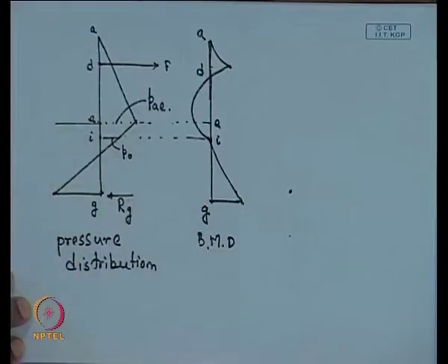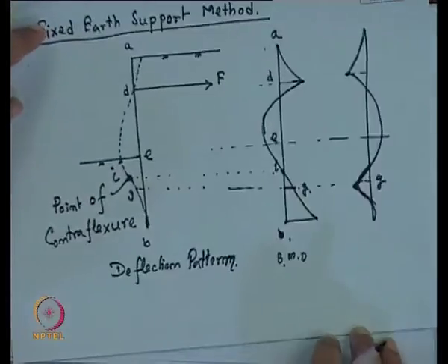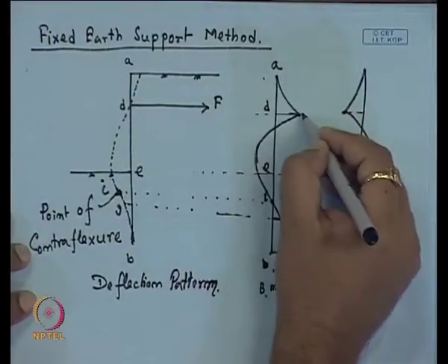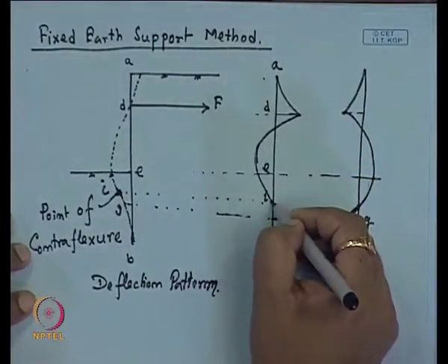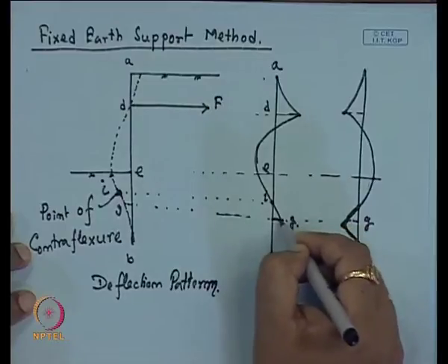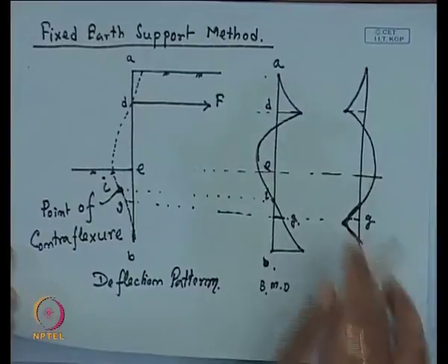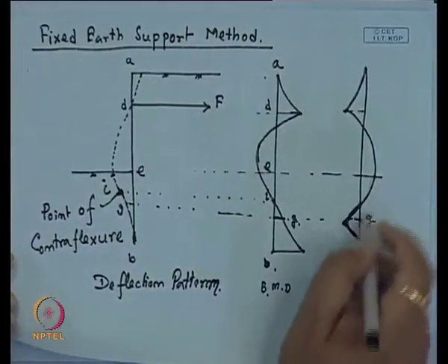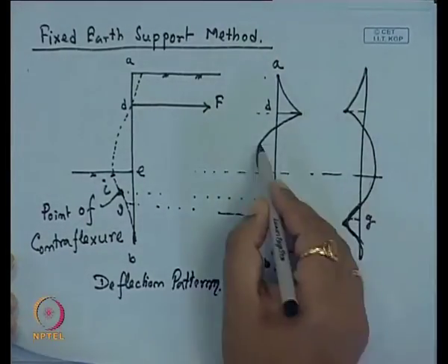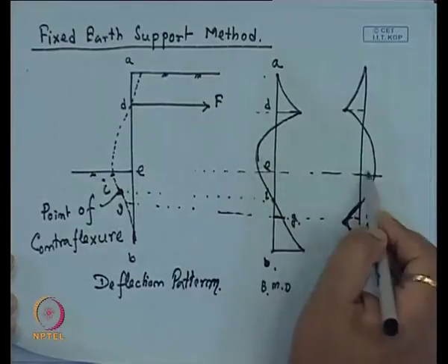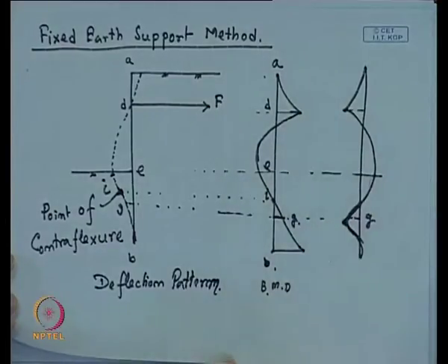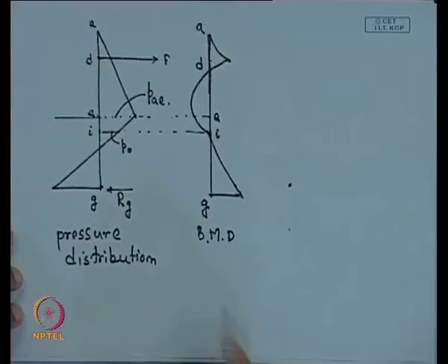This bending moment diagram is similar to the diagram that I have previously drawn. At I it is 0, and we are taking it up to the G portion. So, if I consider only up to the G portion, this will be the bending moment. It is just the mirror image, on the opposite side. So, this is in the G portion, and this is the bending moment diagram.